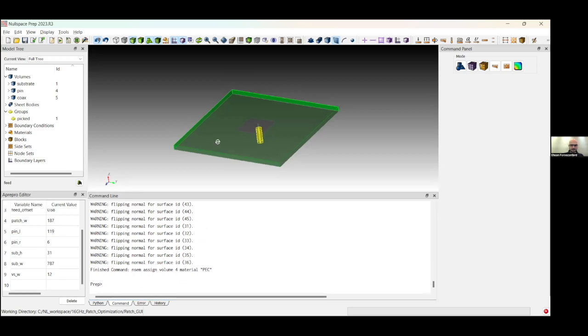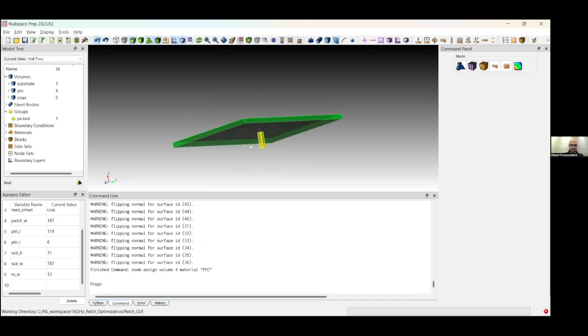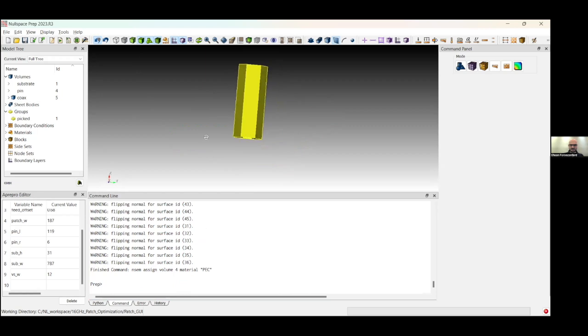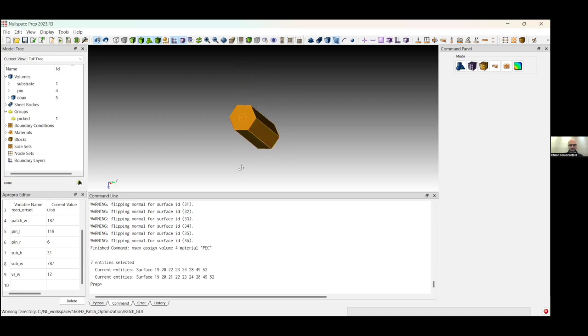And one last thing we need to do is the outer shell of the coaxial connector. So with that, we can go ahead and isolate the coax first. From the model, right click and then isolate that. To be able to see which surfaces to select, you can press Control and draw a rectangle, and then you can see all the selection. Then rotate that to see if there is anything left, hold Control again and then select. So now you can see all the selection that I did.